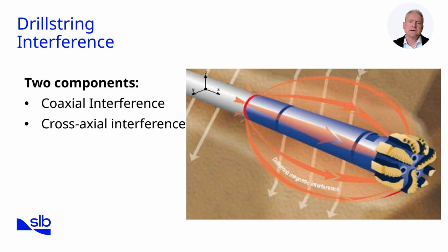Cross-axial interference acts at right angles to the long axis. It is difficult to correct and creates noise that can impact simple corrections, creating no-go zones for these algorithms. The azimuth error caused by axial magnetic interference is a complex function of hole direction, tool orientation, the local magnetic field vector, and the intensity of the interfering field. Often, in high-inclination east-west wells, even with considerable non-magnetic components to separate the sensors, there will be azimuth errors. The inclination is the multiplier, highly deviated versus straight.